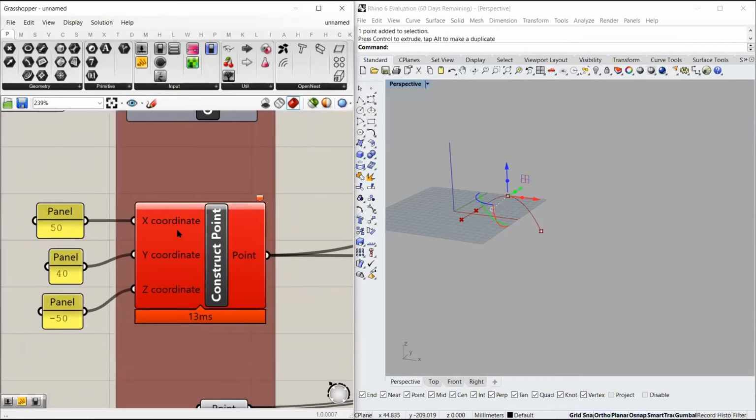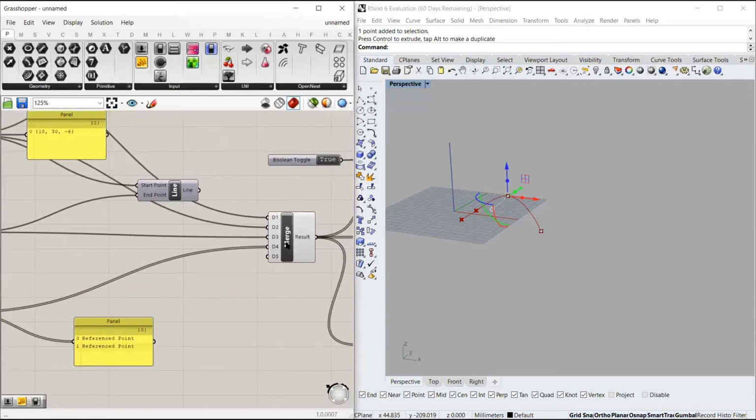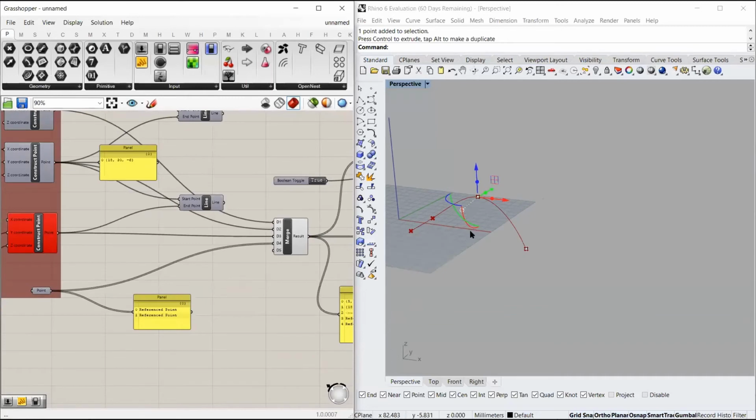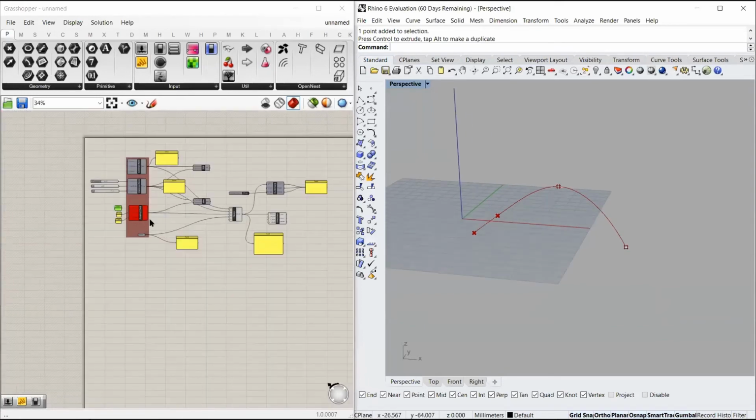Whenever a component shows an error, it turns red with a balloon and it says data conversion failed from text to number, and this is because there is a null value in the second line. Your second point failed to be made, and hence it has failed to be merged over here, and my curve changed, and it changed to make just from these 4 points.